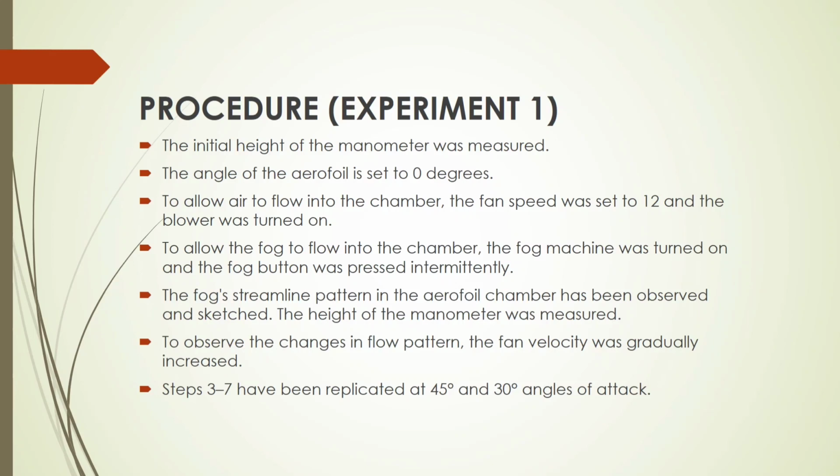The fog streamline pattern in the aerofoil chamber was observed and sketched. After that, the height of the manometer was measured. Then we need to observe the change in the flow patterns, and the fan velocity was gradually increased. Steps 3 to 7 need to be repeated at 45 degrees and 30 degrees angle of attack.